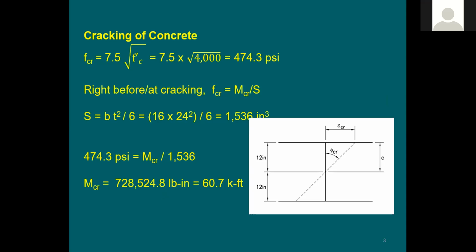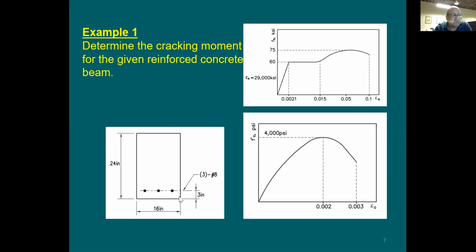Thank you. No problem. Professor, you also mentioned that when the moment reaches 60.7, at that point, the rebar begins to experience tension, you said? Yeah. But we're going to be talking about this next lecture when we start talking about reinforced sections. So what I'm trying to tell you is this. As long as you're below the cracking stress and the cracking moment, this rebar doesn't do you much, because concrete is still good. It is able to take some tension force and tension stress, if this makes sense to you.